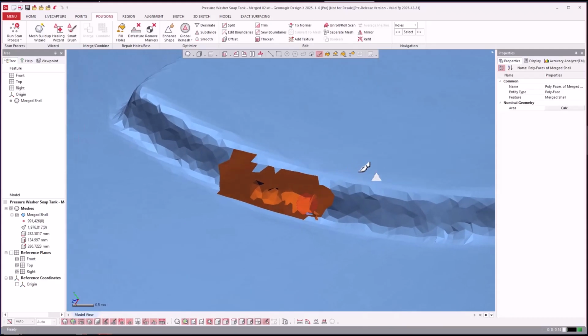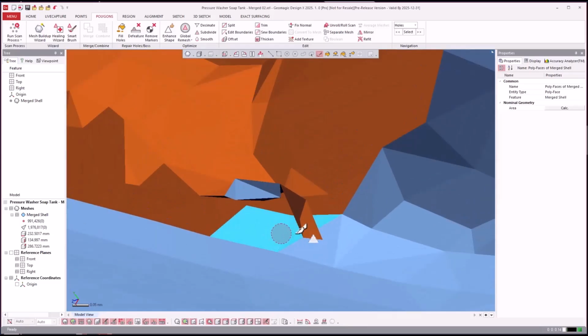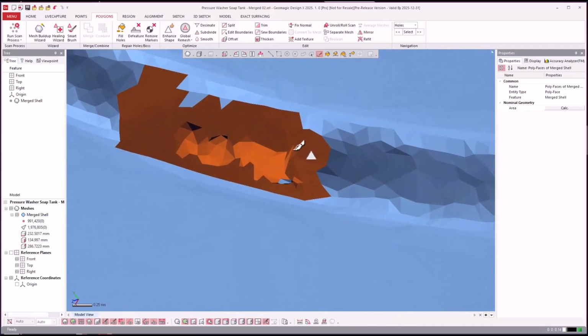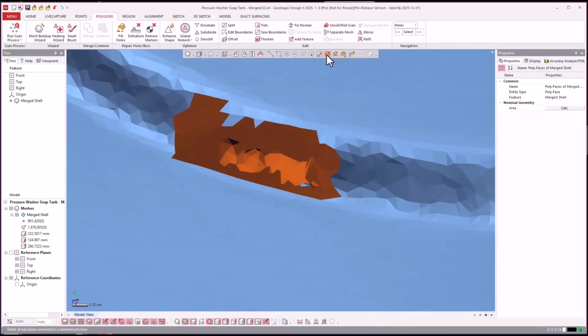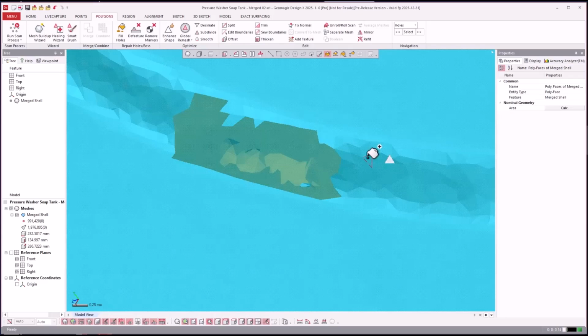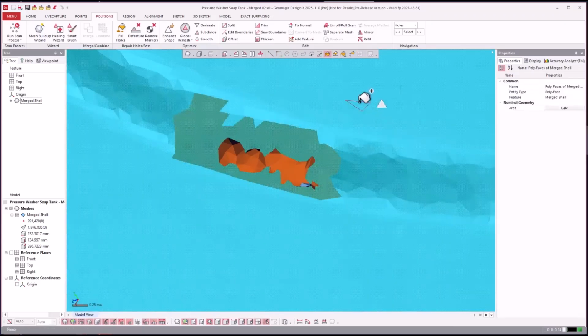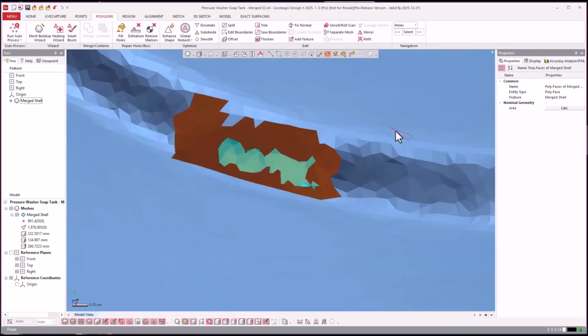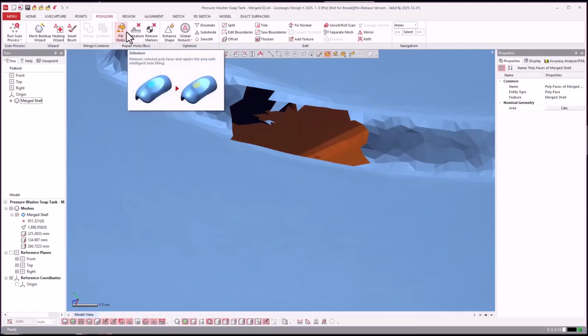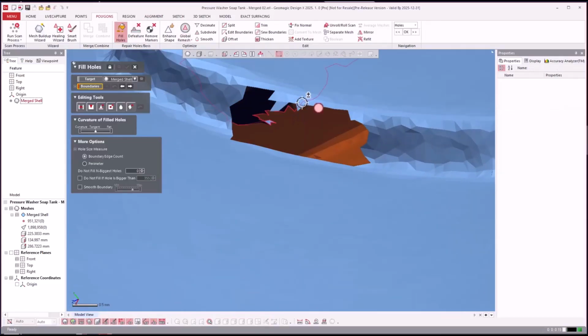just select it, and you'll see that there's some floating bits and things like that. If you have a floating area here, you can do a couple things. I can click on the floating thing itself. I can click on the overall piece. So if I click on the overall piece, this is the classic inverse selection, delete all the floating bits in space, and then come in and do hole fill.